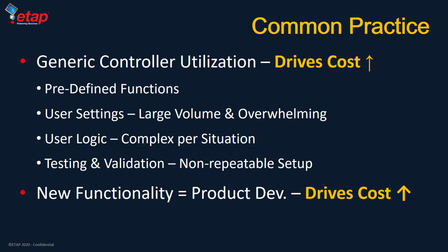Another approach is to develop a generic microgrid controller with predefined functionalities. In this approach, the types of resources, constraints, and overall objectives are part of the predefined functionalities. The main drawback of this approach is that any new requirement of functionality that is not supported by the existing control functions may not be achievable without an additional product development.